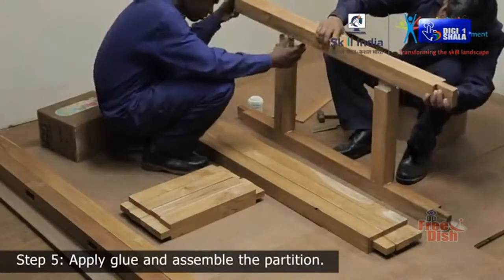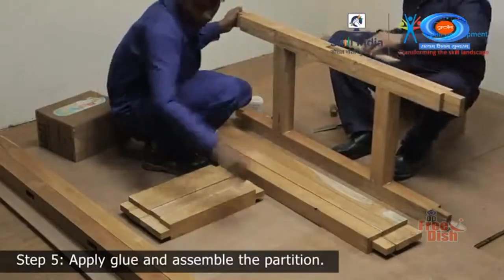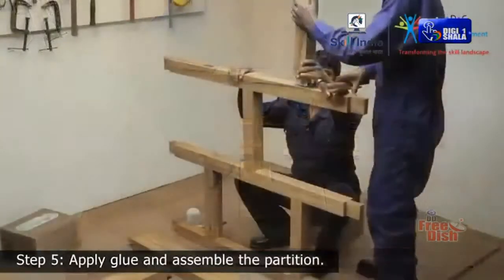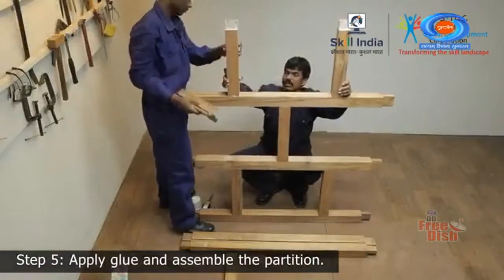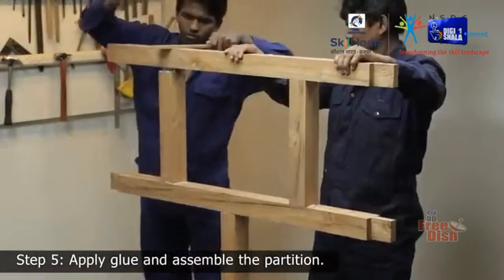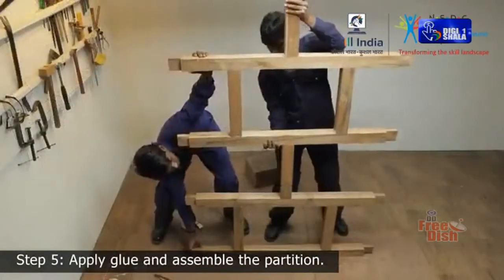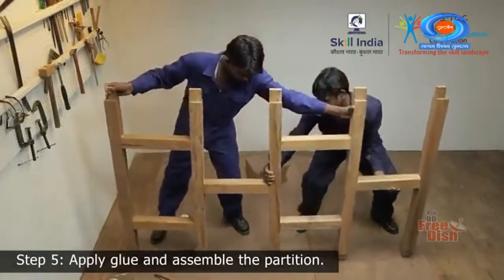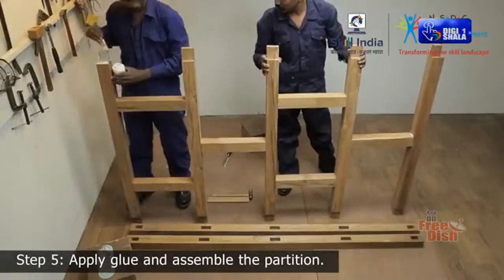Remember, from now on, you'll need a helping hand to assemble the partition further. Similarly, keep fixing the noggins to the stud members part by part, till you have fixed the last stud member of all the 5 members. Once done, ask a helper to help you rotate the frame so that you can fix it onto the top and bottom rails.